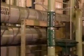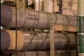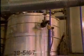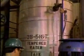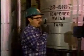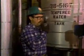When the cooling water pump is started, cooling water will fill the shell side of the heat exchanger. Any air that is trapped on the shell side escapes through the open vent valve. As the shell side of the heat exchanger fills, the operator listens for air escaping. When the shell side is completely filled, he calls the control room and has them shut the vent valve.